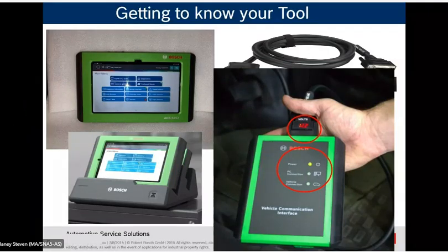What happens if you plug it in and there is no power? Does it light up? Usually that is just telling you that there is something wrong with the power feed at the diagnostic connector, pin 16, and it usually comes down to a blown fuse. Or, gosh, I've been seeing a lot these days, guys hook lights up to their snow plows, and they somehow fasten it to that wire, and sometimes it'll blow that fuse.